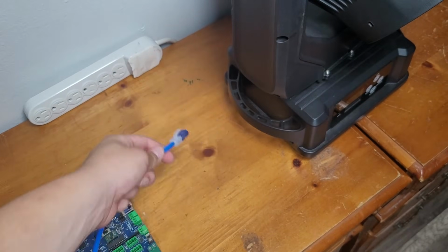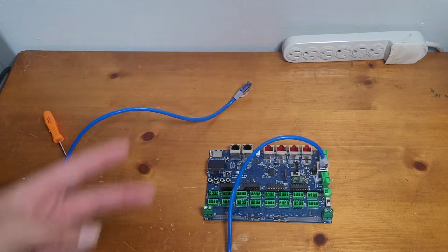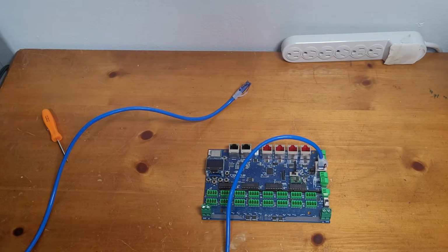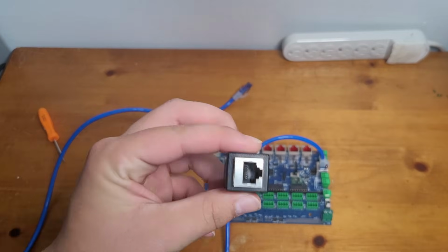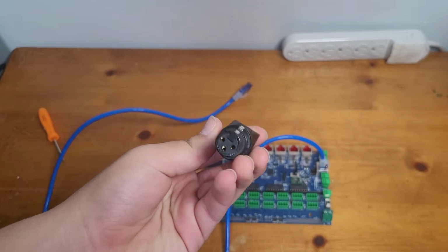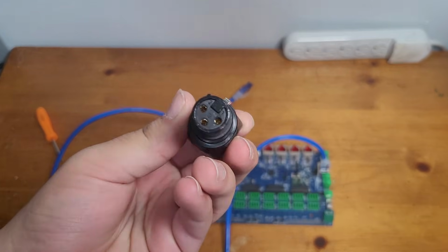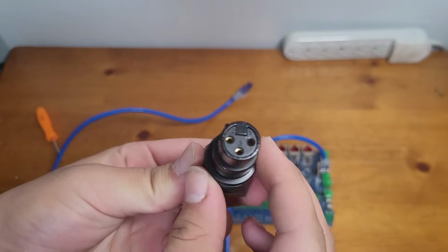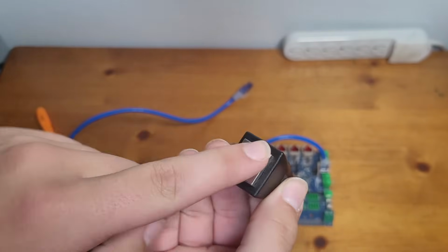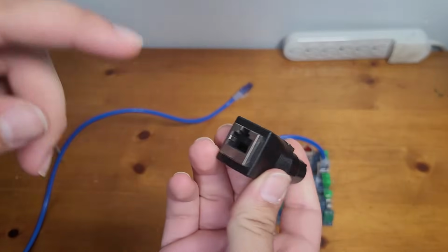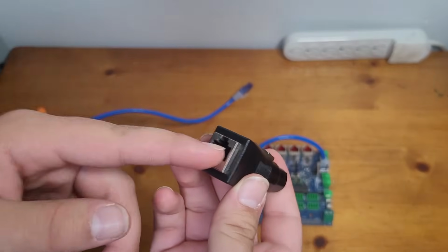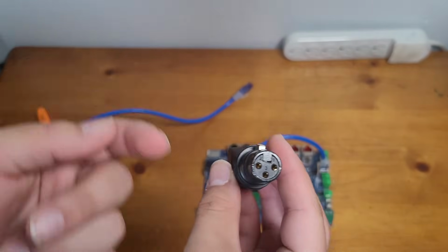But there's nowhere to plug this in, so how do we handle that? Well, you have 2 different options. First is you could buy some sort of adapter similar to this, where it will take that Cat5 cable and convert it to an XLR connector like this. So this could plug right into my DMX device, and then I could plug the cable in here. And normally the wiring is all correct, so it takes the correct pins from the Cat5 cable and puts them to the right pins for XLR.